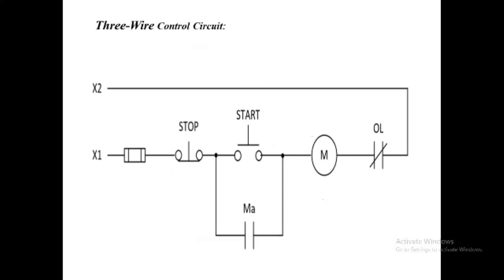Here, control wirings are given. There are two common types of control wiring. One is the two wire and one is the three wire system. Here, this is the three wire system. A two wire control circuit is not shown, but a two wire control system requires the start signal to be a maintained contact. This can be a maintained push button, limit switch, float switch, logic controller or other sensing device. When the motor is starting, the current flows through the starting device to the contactor coil M, and current continuously flows through the device until the motor is turned off.